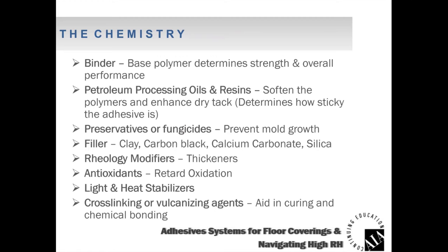So looking at the chemistry, the term binder is basically the base polymer that is holding the floor covering to the substrate. The strength of the material is coming from this binder. The overall performance of the flooring is coming from the specific binder, holding that floor covering to the surface.